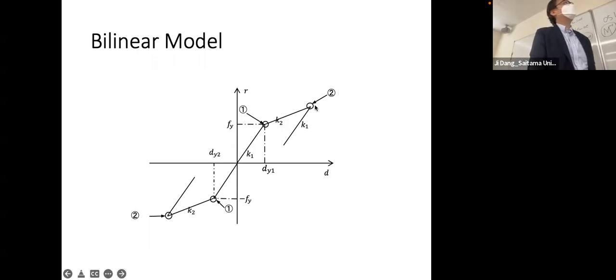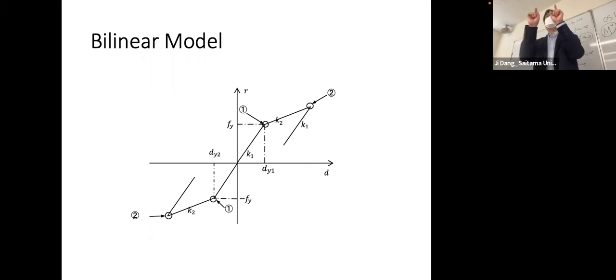The stiffness will not follow K2, but will go down by K1 because of the unloading effect. We can have this kind of experience when you are bending a steel wire, then you take your hands away, and you will keep the shape, right? You keep the shape because the wire is under plastic loading. So the shape change is the residual displacement due to the loading.